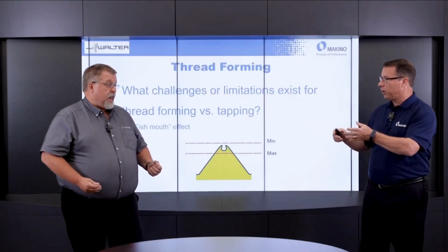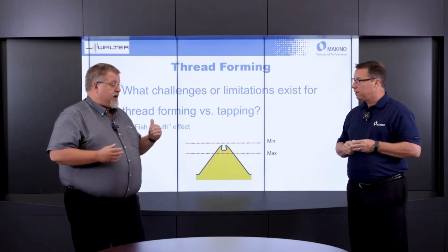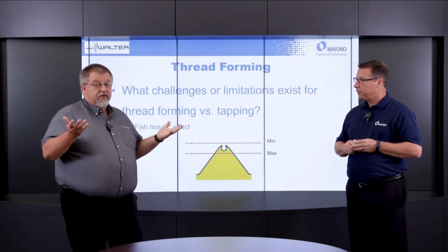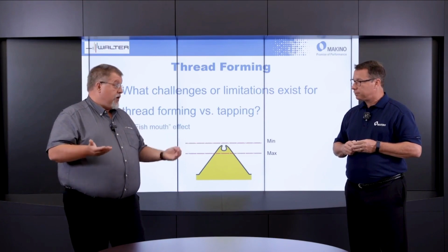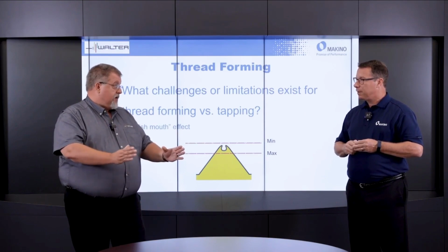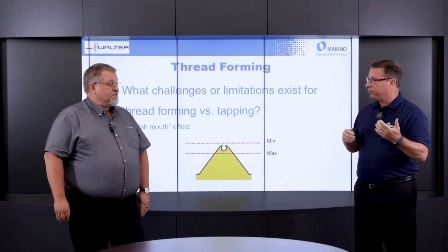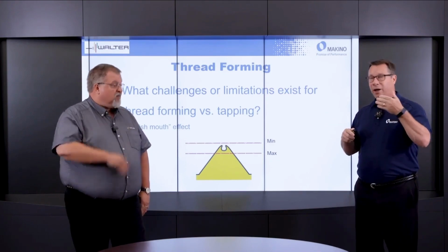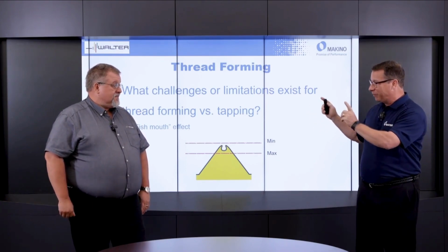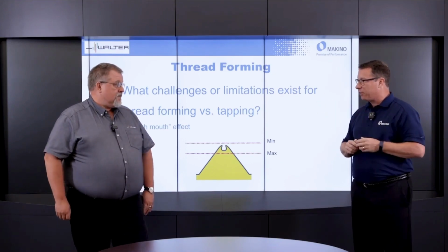Any other limitations from the standpoint of where you might not be allowed to use it? Yes, there is another really big one, and that's going to fall onto military and aerospace applications. Please check with your end user if you can form thread those parts before doing it. There are limitations that they have to make these parts out of a homogeneous piece of material, and cold forming it will violate that. Kind of interesting as a side note, with my past experience here at Makino as a process engineer, we have actually seen the opposite, where we've seen automotive part prints come out which specify that thread forming must be used. I think what they're really after is the strength of that thread. Exactly.